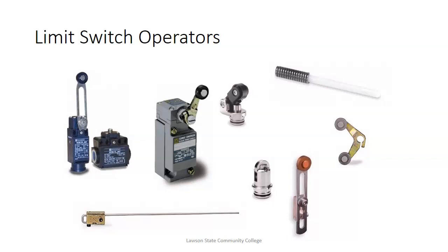Like I said, these things have been around for years. They're very, very rugged. The biggest problem we have with them is they're electromechanical devices. So that means they could fail mechanically or they could fail electrically. The biggest problem we have is people not mounting them correctly, and they exceed the range of the operator, and it breaks off, or they bend it, and then all of a sudden it's not good anymore.